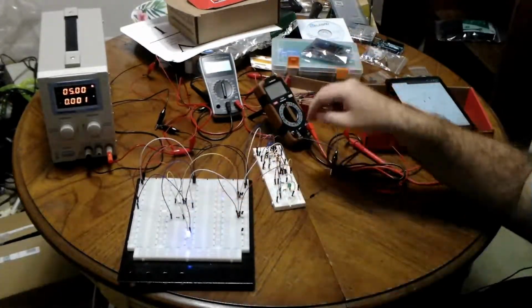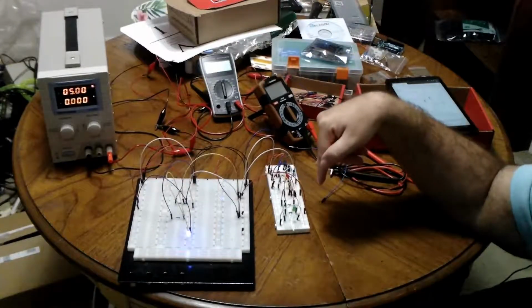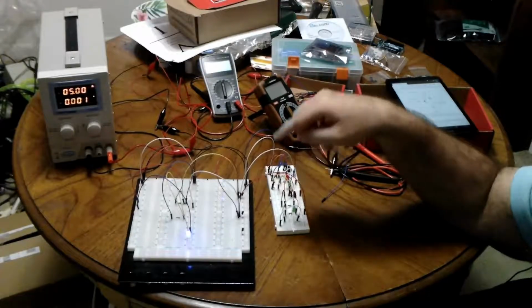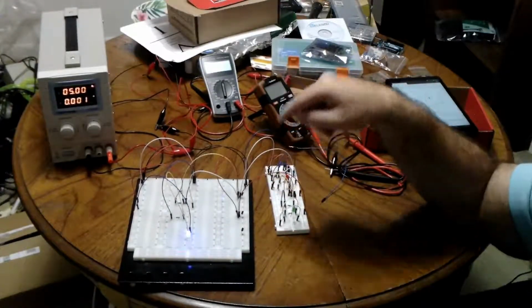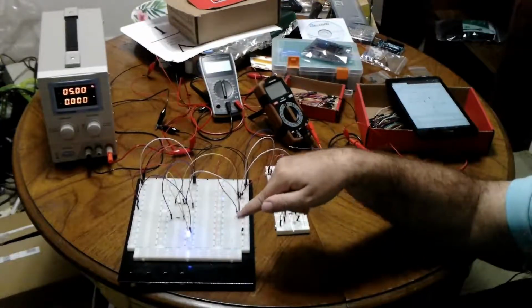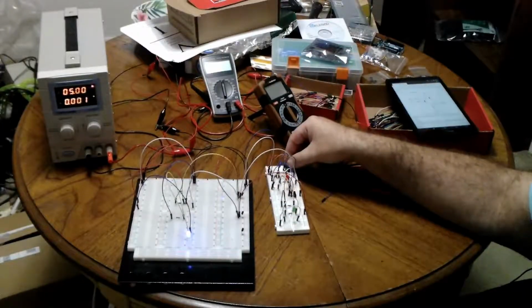But right now, both inputs are off, and that is on. That's what we want, because we have a NAND gate here. For a regular AND gate, both of them must be on for the output to be on. Otherwise, the output is off. So we flip it. Instead of saying both of them are on to turn that on, both of them are on to turn that off. Otherwise, we turn that on. So if I turn one on, it's still on.